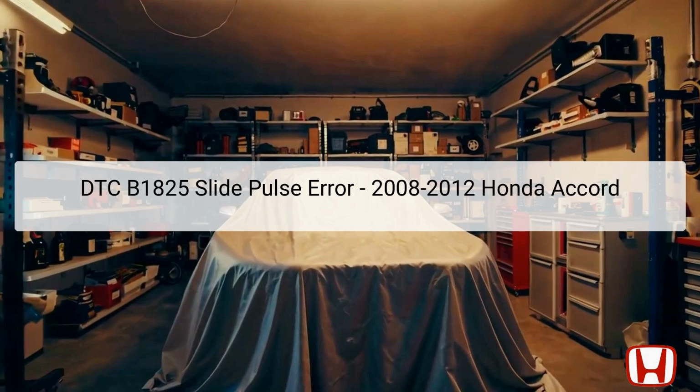The diagnostic trouble code, DTC B1825, is a slide pulse error for Honda Accord models from 2008 to 2012. This error indicates that there has been no change in pulse for a duration of 1 second while operating the power seat adjustment switch. The power seat system allows for various adjustments to enhance driver and passenger comfort, and it is critical for maintaining driving ergonomics.